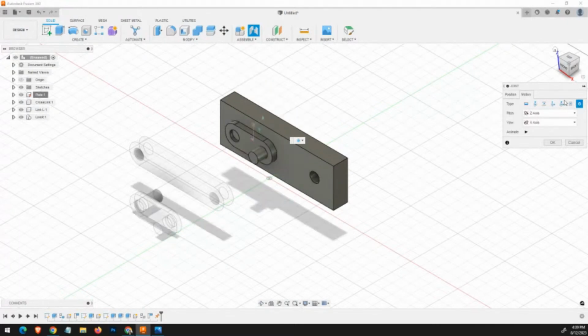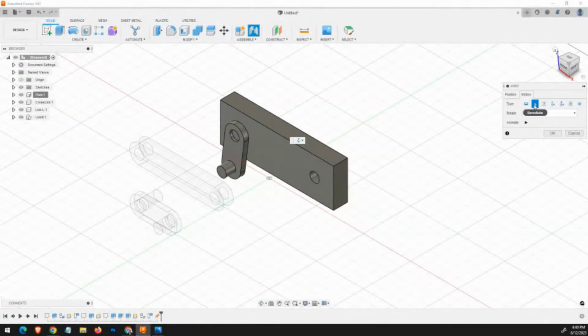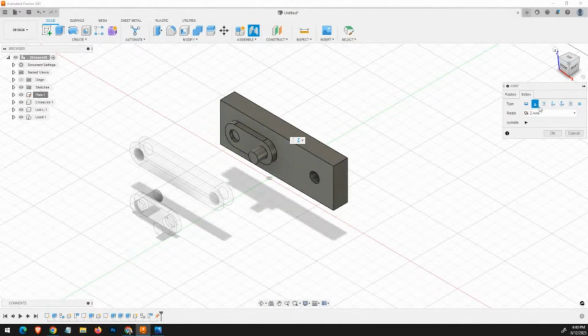I won't ask you anymore which is the possible animation or motion for this. I hope you can follow along too. This one, what we need to put, what is very fit for our assembly, is revolute. See? That is what happens if you use revolute. Once applied and attached, you can click OK.